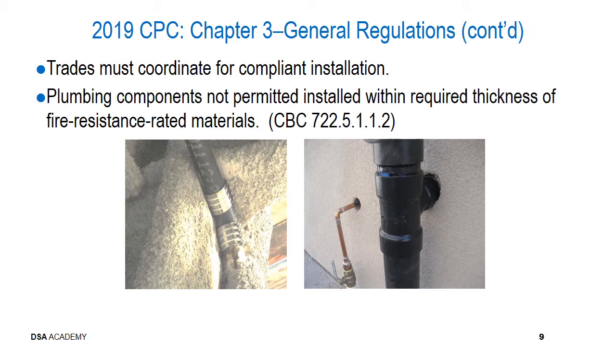So the thing to do is to observe this issue, maybe contact the spray applied fireproofing installer to have them come back and review this and check to make sure that the underlying application of the fireproofing complies with the plans and the specifications. However, if it does not, then obviously a deviation notice should be issued based on fire life safety concerns. And of course, that deviation notice can be issued or generated on a DSA Form 154 and transmitted to the contractor and distributed to all of the appropriate members.